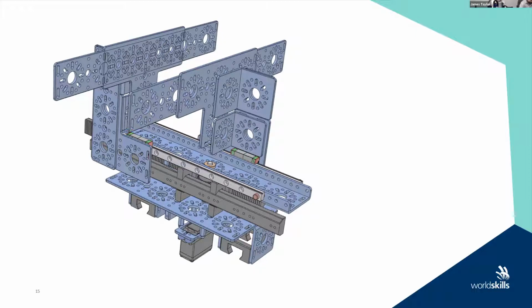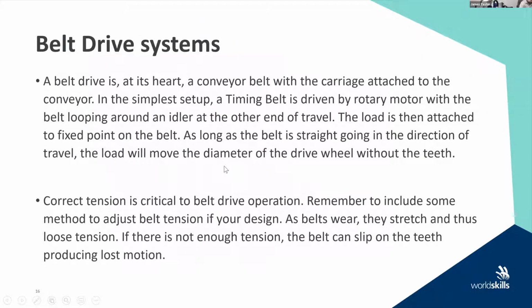As I said, our idea here was to build one mechanism that used the DC motor and one mechanism that used the servo motor. Remember that when we did our last elevator, our 3-hour session on the elevator, we actually used one 250mm linear slide and one servo motor. You could actually build some sort of mechanism like that if you wanted to as well, and put that across the top. But we're just trying to be a little bit more complex when you're doing it, and to give a little bit more support. Okay, this system is going to use a belt drive to drive it. So there's a couple of things. Essentially, it's a small conveyor system.